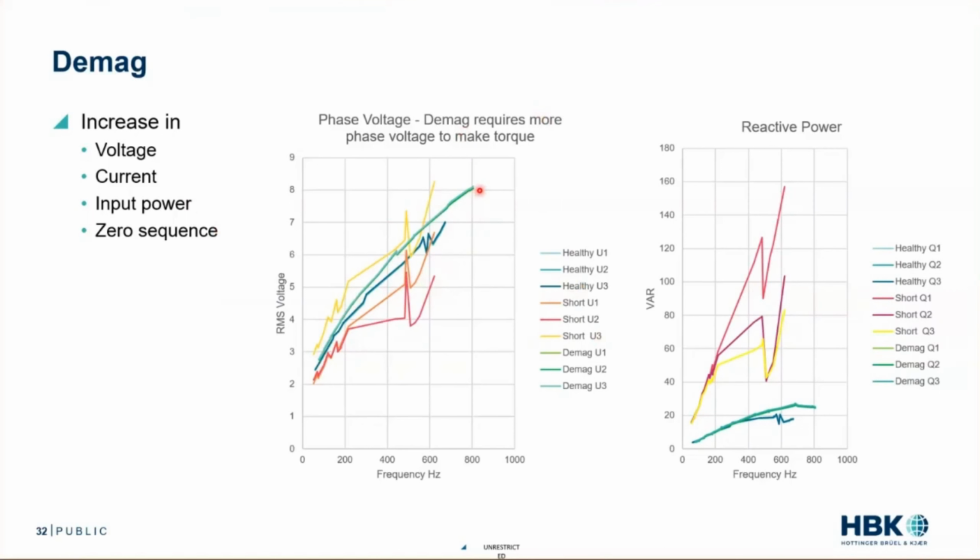Why an increase on input voltage? Well, the flux on my rotor is smaller, so I need to provide more voltage on my stator, more voltage from my inverter to provide that same flux to get that same torque output. So we see, this is subtle, but not that subtle. We can start to see this failure creeping up. This is really cool. We can see that little tiny failure, and I'm pretty sure this was an asynchronous, but we see that. That's statistically notable.